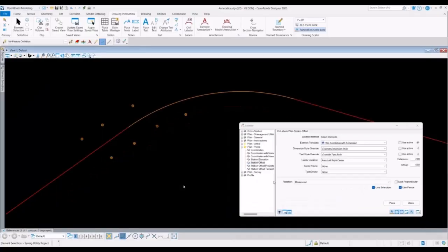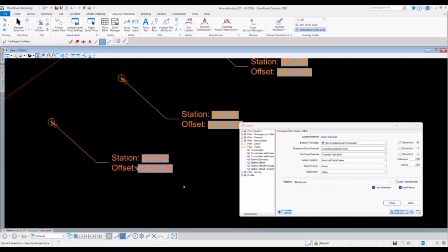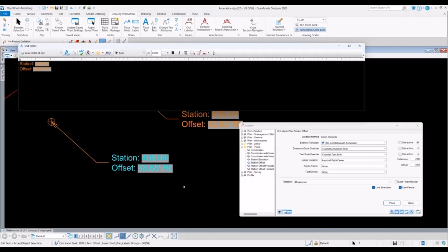So in the instance that you have multiple points using the same exact civil label definition that you're trying to call out, rather than individually placing, which of course doesn't take that much time, right? You can use a selection set or a fence and place the label relative to geometry, just data pointing in space, and then manipulate the placement from there, right?